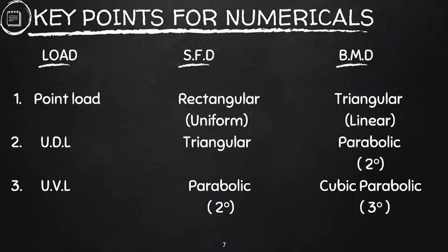Here are some key points for numericals. In the very next video, we will try to solve some numericals of strength of materials, on shear force and bending moment diagrams. Before solving those numericals, you need to learn these points for drawing shear force diagrams and bending moment diagrams. When we have a point load, the shear force diagram is rectangular and the bending moment diagram is triangular: a rectangular uniform diagram and a triangular linear diagram.